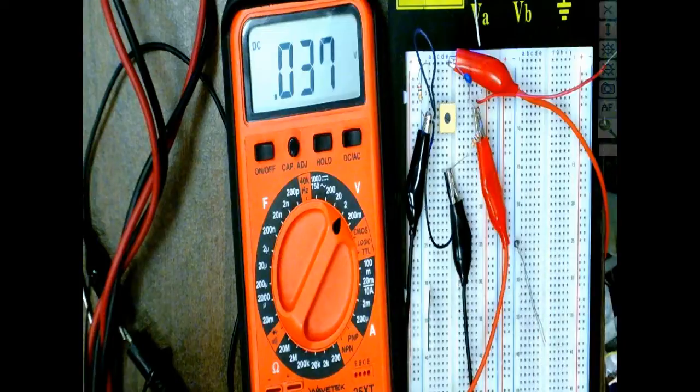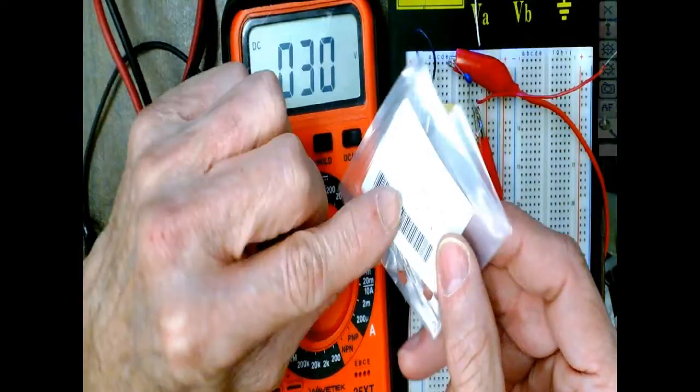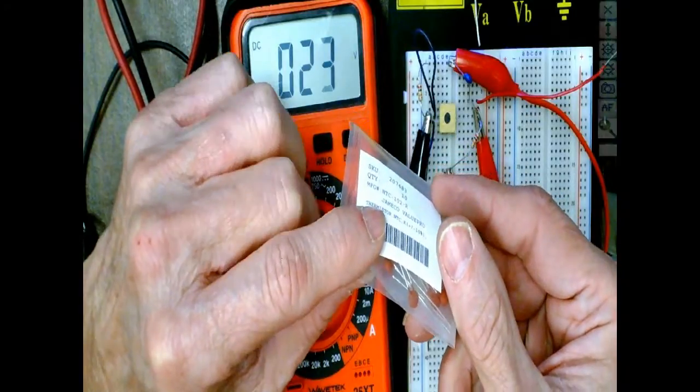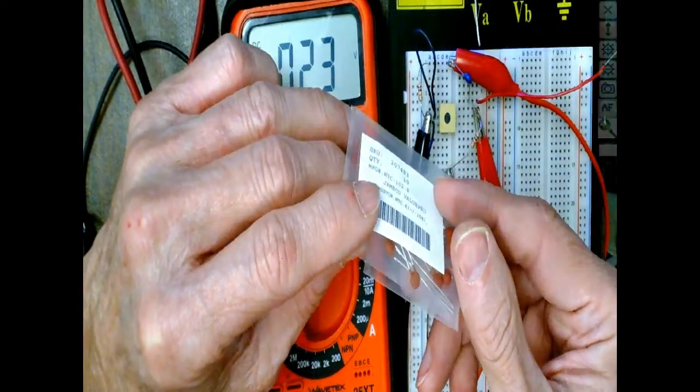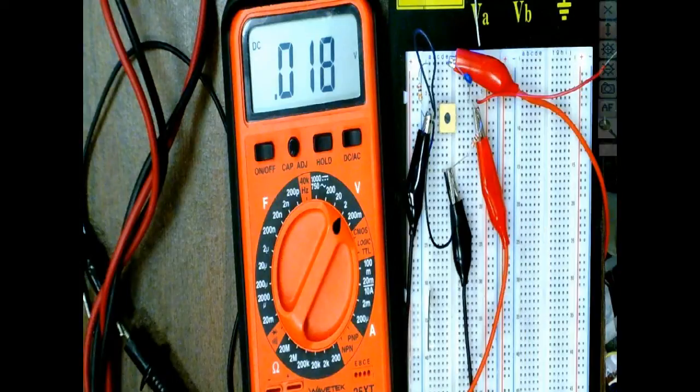And then we have these right here that I haven't hooked up yet. These look a lot like capacitors, but these are NTCs. NTC 10. We can look this one up and probably get the data sheet on it. So that's probably what I need to do, and that way I can show you all the actual chart for true thermistors. You'll run into these things all over the place. Like I said, using electronics, we can compensate for their non-linearity. If approximate temperatures are needed, then these guys work great, especially if it's used over a narrow range, like in your HVAC system you have at your house when you run your air conditioning.